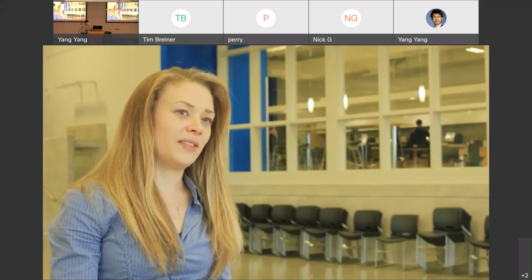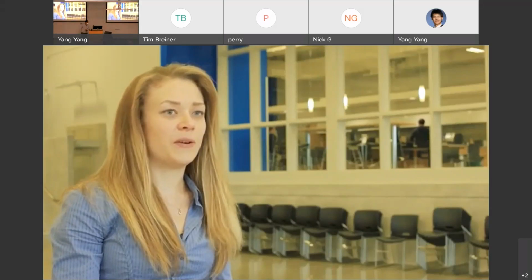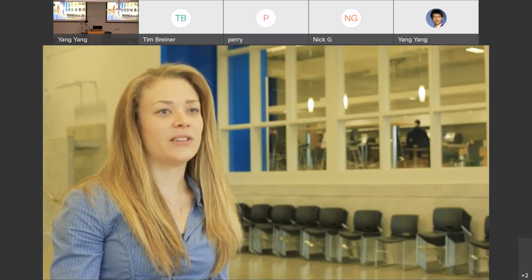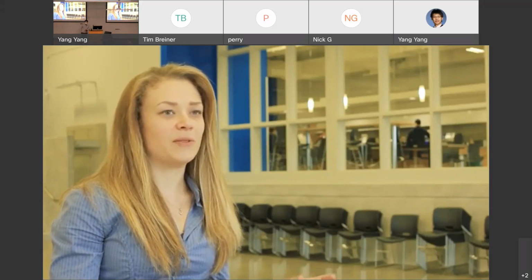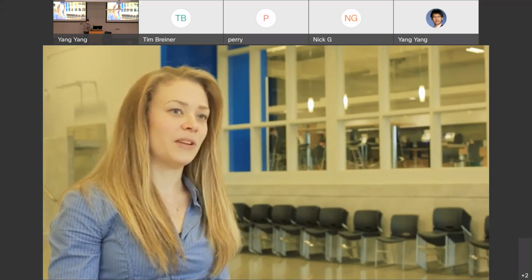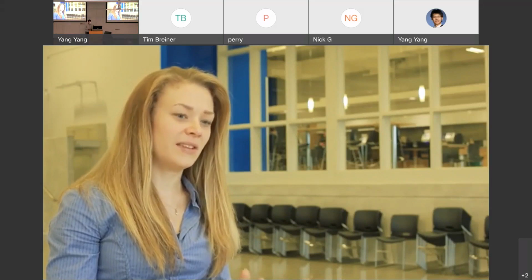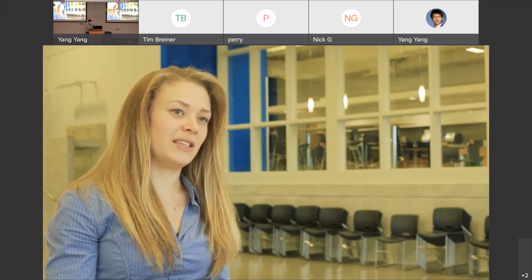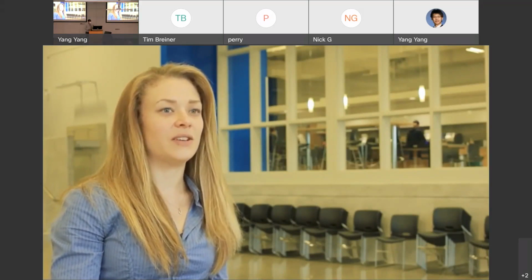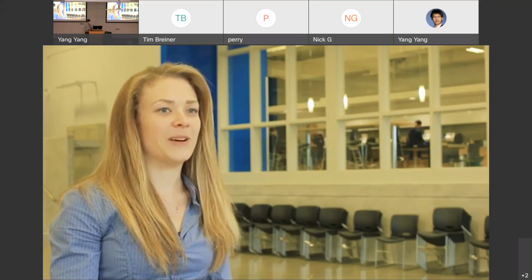We worked closely with the structural engineer to determine the preferred TMD masses and locations, and then we constructed a model which represented the crowd structure TMD system. And this model actually incorporates 4 separate dynamic systems: the floor structure, the TMDs, the dancers, and the passive crowd. And we were able to use this model to show how the TMDs could effectively mitigate the floor's response.